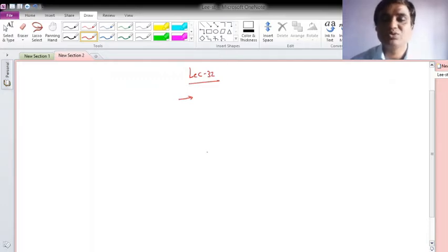If I am nullifying the sources, the voltage source should be short circuited and the current source should be open circuited, and then find the current. Similarly, next time you activate another source, deactivate all the others, and find the corresponding current. You repeat this until all the sources are finished, and then the resultant current is the algebraic sum of the currents. That is what we have seen.